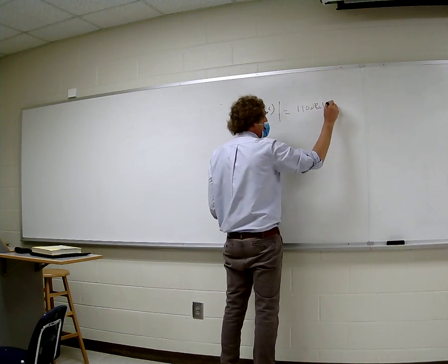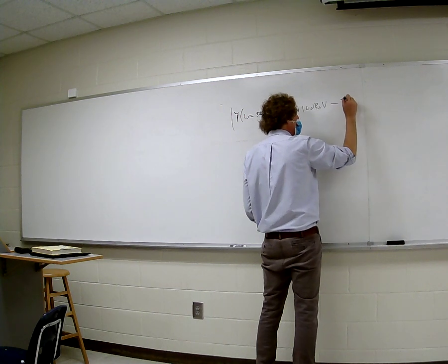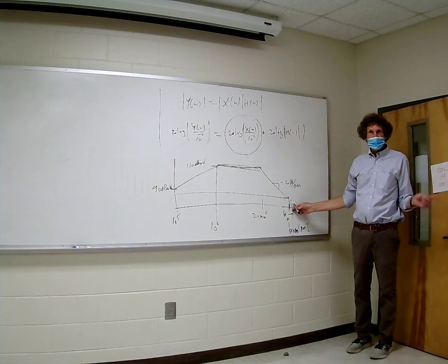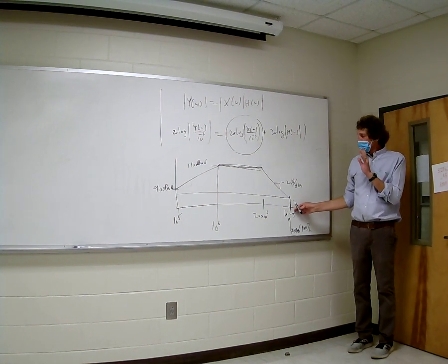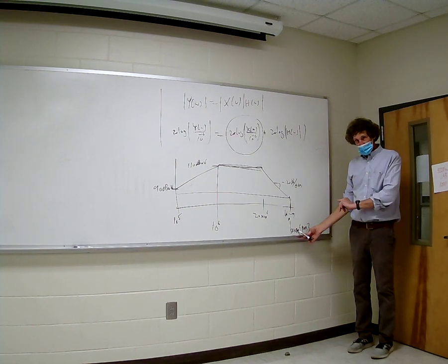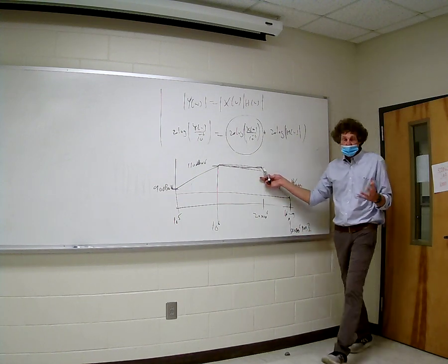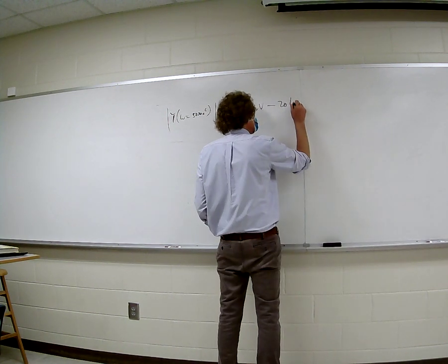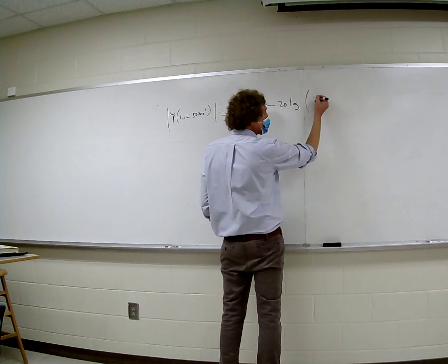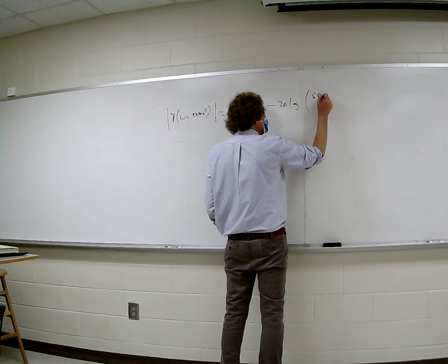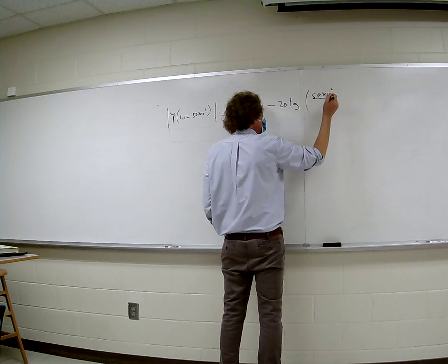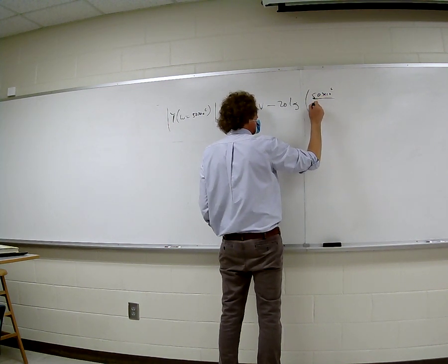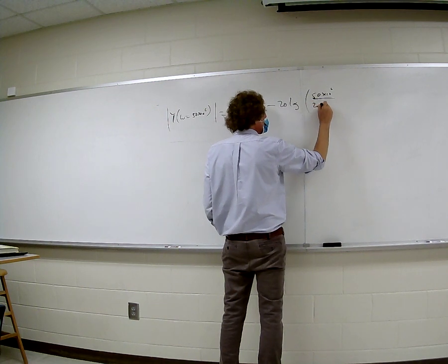dB microvolts, right? Then I subtract 20, because now it's going down to 20 dB. And what's the value going to be? Well, 20 times the log of the upper frequency, that's where I want the value at, divided by the frequency the break started. So it's 20 times the log of the ratio. The upper frequency is 50 times 10 to the 6 radians per second divided by 20 times 10 to the 6,